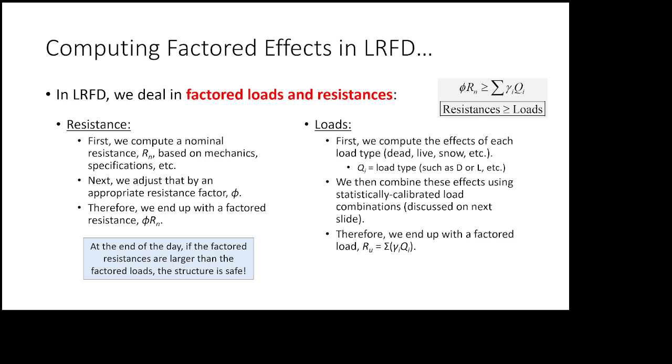And so what we then might say is, let's say this is, I don't know, 800 pounds. Instead of using this Rn, this nominal resistance, we use a design resistance. I think that's like 640. And so instead of the 800-pound nominal resistance, we have a usable resistance of 640 pounds. And that's been reduced according to the associated uncertainty.